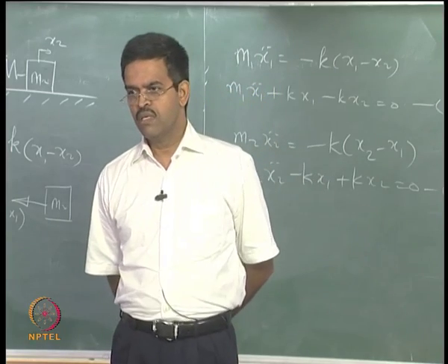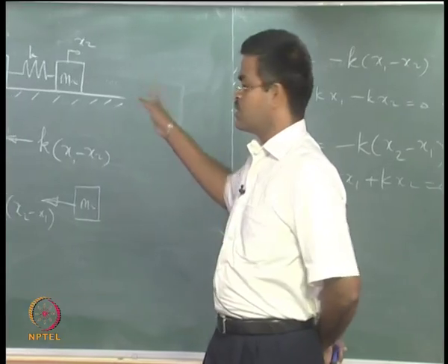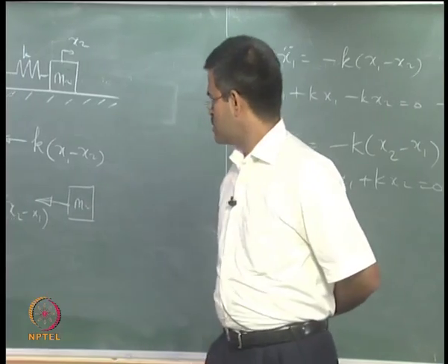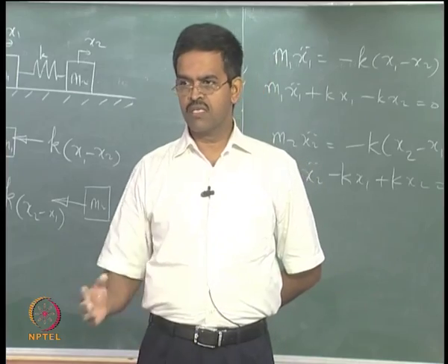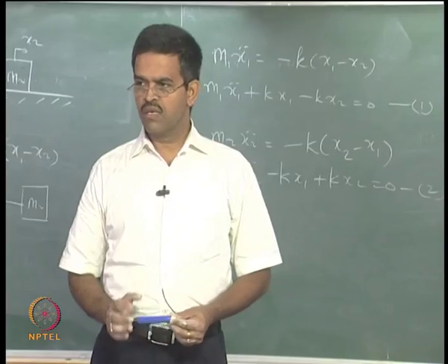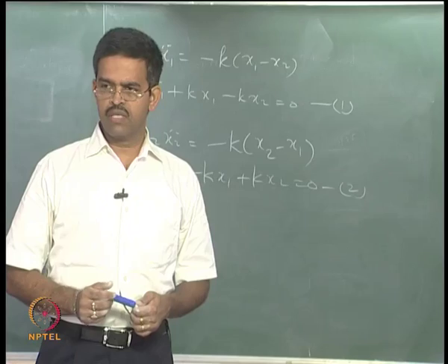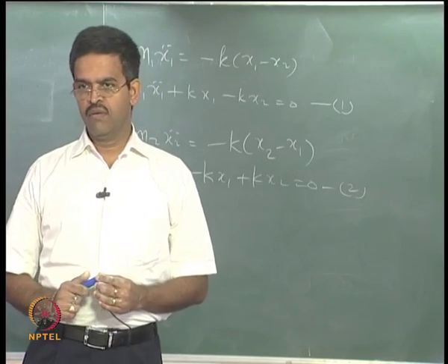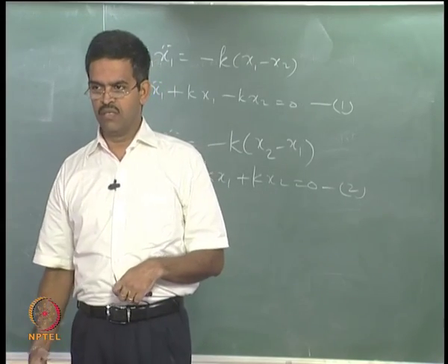How do I write my equation of motion, because I do not know how to derive my mass matrix? In this case it is simple because the mass matrix becomes diagonal. There are cases where the stiffness matrix also will become unsymmetric. Let us see these special cases as we move on. In general, stiffness matrices are square and symmetric. They may still remain square but may not remain symmetric. There can be axisymmetric terms which will influence the response behavior of the platform in certain cases, we will see.